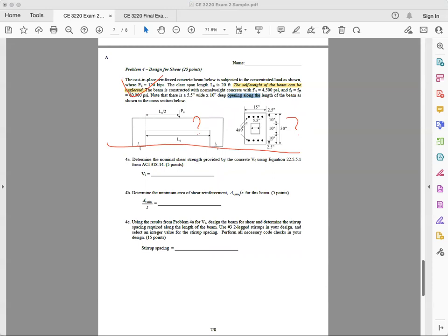One hint. I am doing a beam like this, right? A rectangular with an opening in the middle. What if I end up with a T-beam or I-beam? What if I end up with this? I have reinforcement here, reinforcement here. How do I do this? Well, it's the same, right? The only thing that changes is that bw is now the web width, the width of the web.